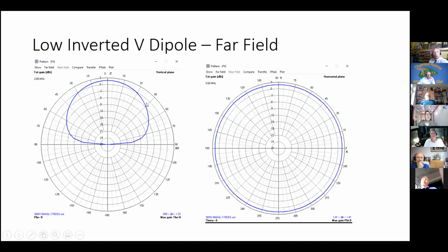We first of all have a look at the far field. And what we find is that it is a very good radiator straight up. This is an NVIS antenna, primarily near vertical incident skywave. There is no gain worth having flat to the ground, and it has about 2 dB of gain relative to isotropic straight up, and a bit more than.